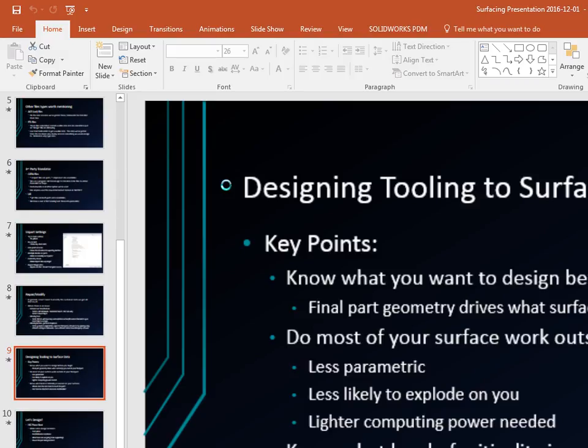Hide that. Okay, I'm going to take these edges. And just as an example, I'm going to take a small section of them. If you work in small sections, then you can break it down to like 4 plots instead of trying to do all as one, and then you can take those 4 and make them all one. So here I'm just going to straight up do a fill surface in there so that it's just one surface. So now I've got a filled surface that I can replace those faces with this single surface.